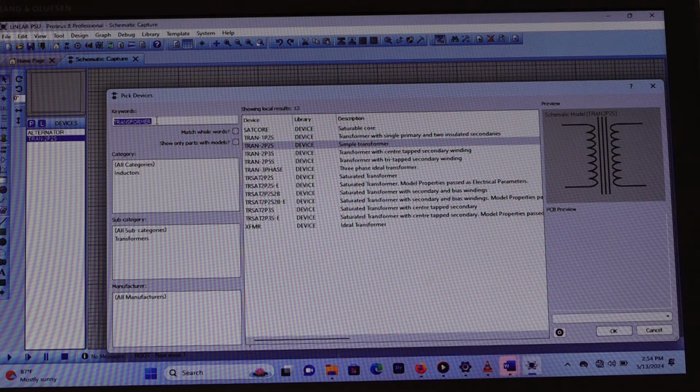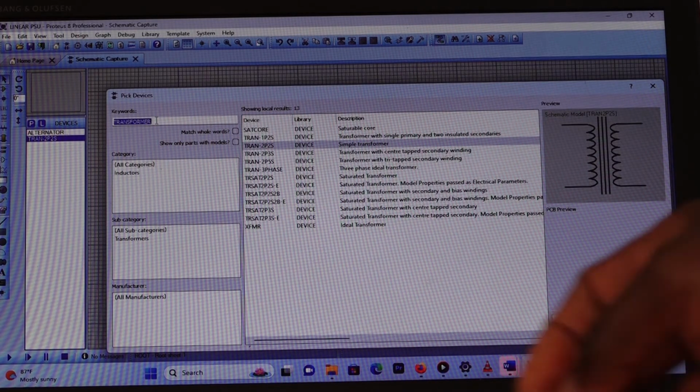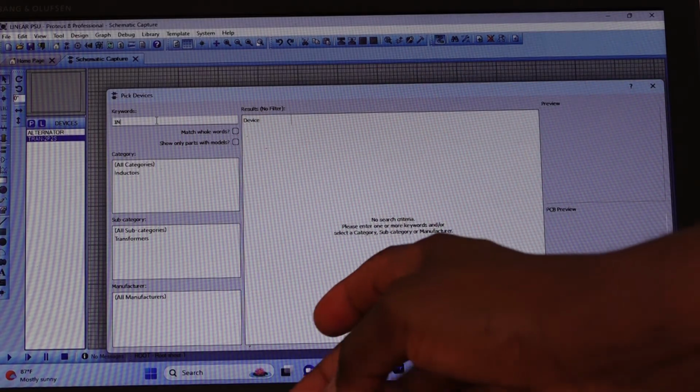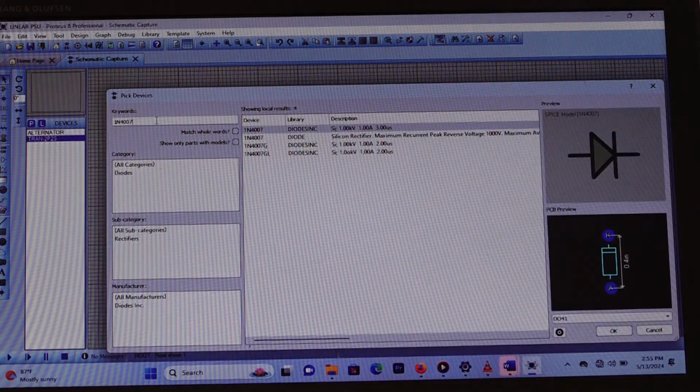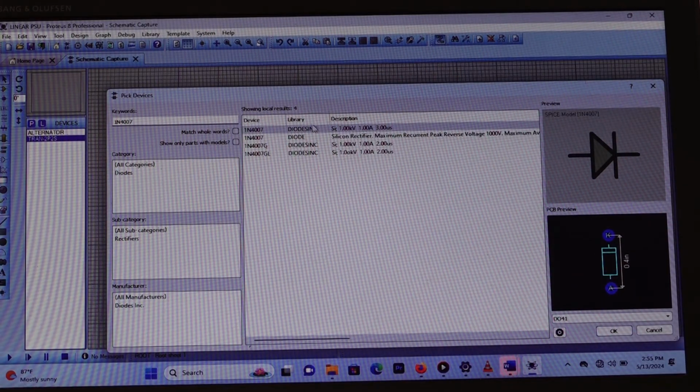We may implement the rectifier. Students, I said, attention please. Attention, look on the blackboard. Then we may implement the rectifier by selecting a rectifier IC, or integrated circuit, or we may implement the rectifier by using individual diodes, general purpose diodes. So you are going to implement the rectifier unit by using general purpose diodes. The general purpose diode, according to the schematic circuit diagrams, is 1N4007. You just write 1N4007. Then you have this one.